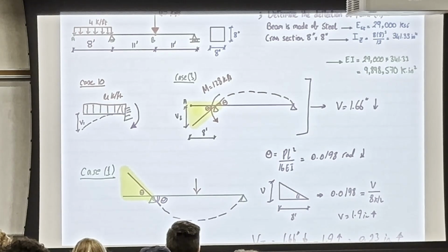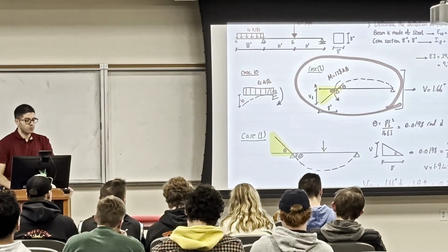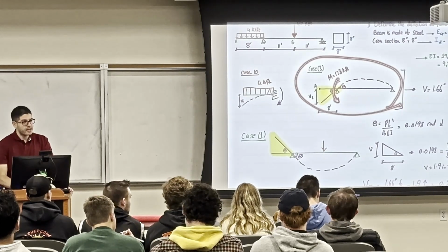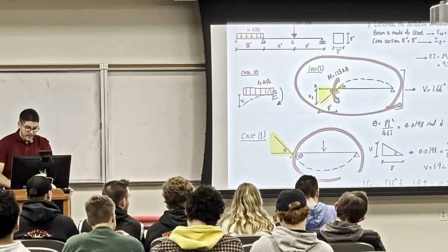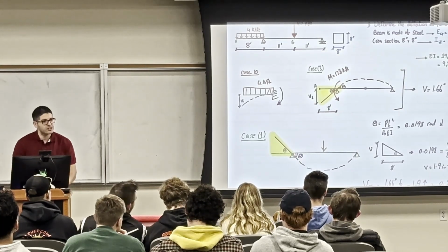How many load cases now? 2. That's correct. Not one case. So you're gonna use this load case, which is load case 3, which you have a bending moment that takes the effect of the cantilever, in addition to that point load. And now you don't need to find the theta or the triangle or anything because it's the deflection at the midspan.